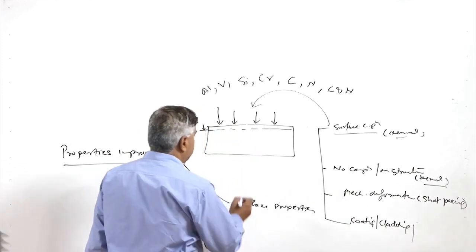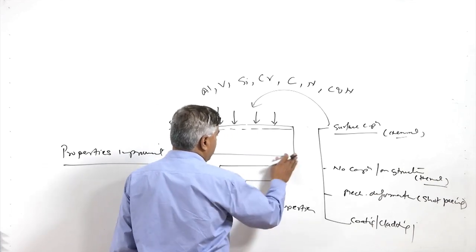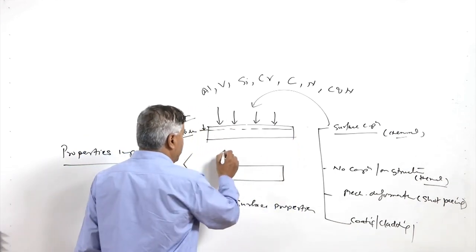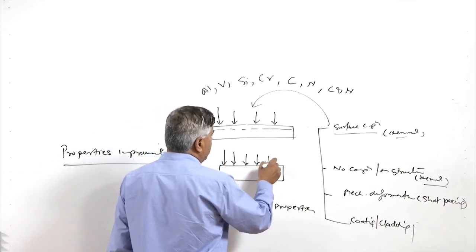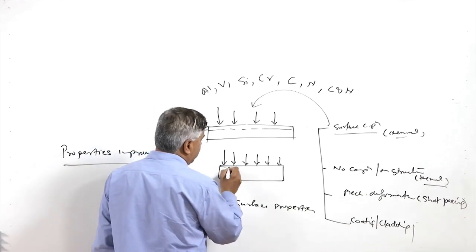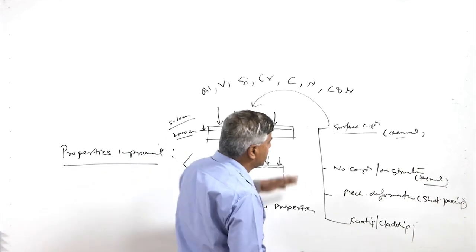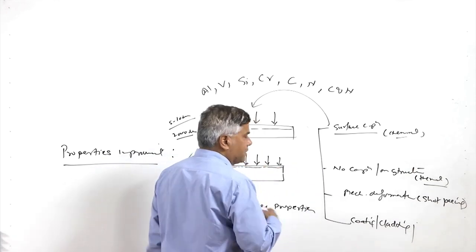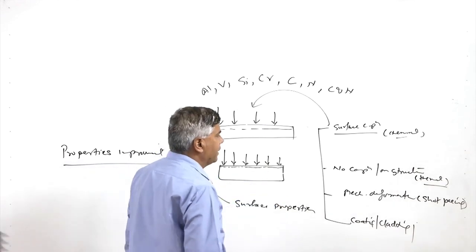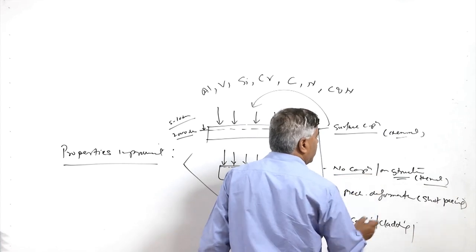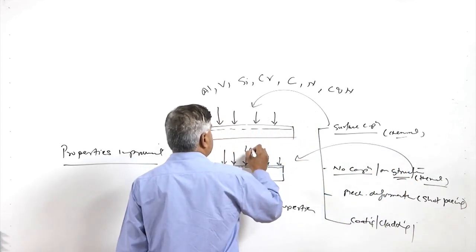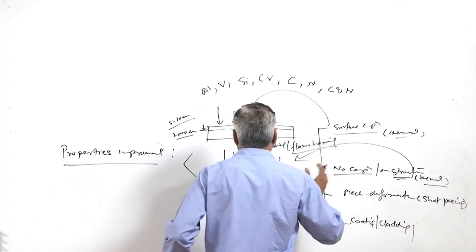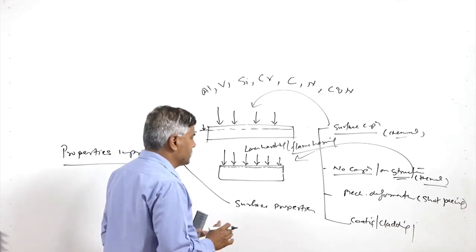Another method is where just thermal treatment is applied. In this case, those kinds of metal systems which experience structural modification whenever heat is applied are used. So, controlled heating followed by cooling results in structural modification near the surface. This is the kind of approach used for modifying the structure as per the requirement, so that the properties of the metal at the functional surface can be modified. This is what is tried in the case of no compositional modification, just structural modification. Laser hardening and flame hardening are these kinds of methods where no composition modification, only structural changes, are brought in at the surface of the material.